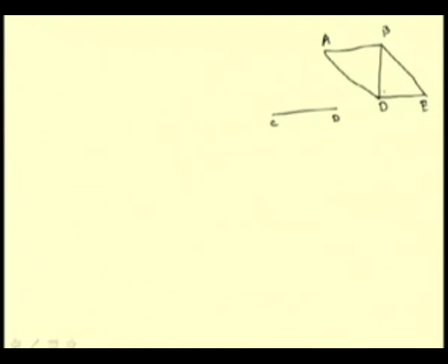So, now for each of these free body diagrams, let us depict what the unknowns are. At A we do not know the two components of reaction, that is Ay and Ax. At D we do not know the two components again, that is Dx and Dy. If we come to this element CD, at C it is connected by a pin. So, again we have two unknown components of reaction, that is Cy and Cx, and at D we have Dy and Dx. We can observe that since D is the common joint between this element and this element, the forces are equal and opposite.